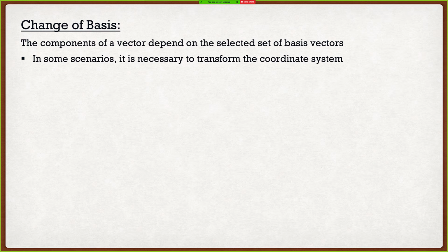And you say, Clayton, well, give me an example of that. Well, let's take material properties of something. What we do when we measure material properties is we measure them in certain directions. The best example is wood. You guys know that wood has those nice vertical fibers. Therefore, we actually have to measure along that vertical line and then perpendicular to it. So if we were to load a piece of wood in a direction that's not aligned with those wood grains, what we actually have to do is transform our load to match the direction of those wood grains. Now, this is something I'll show you guys a lot more in depth later. I'm just trying to show you guys what exactly this means.